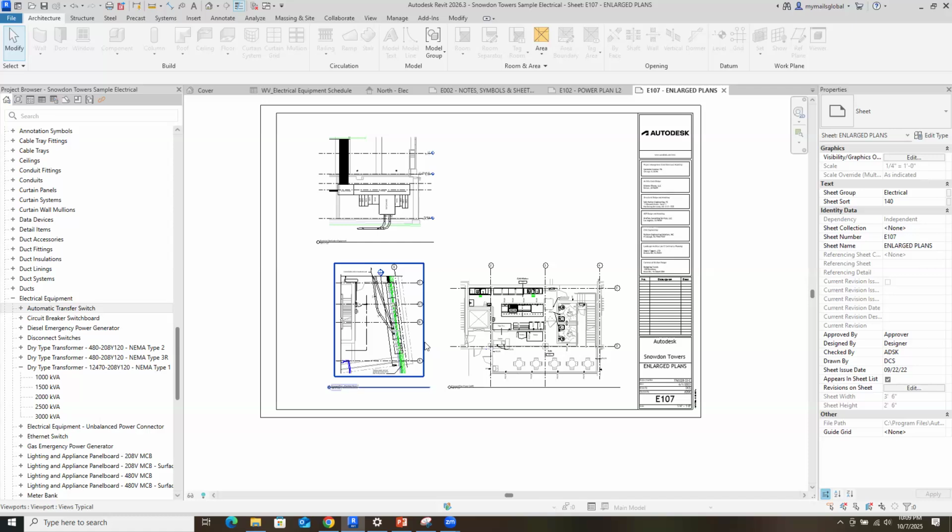Then there are certain modeling standards, and how to coordinate the models. Intervals are set to coordinate the different models, like weekly clash detection or model purge, set coordinates, etc. And while doing deliverables, how to extract the drawing files and how to extract the schedules, that we can do here.